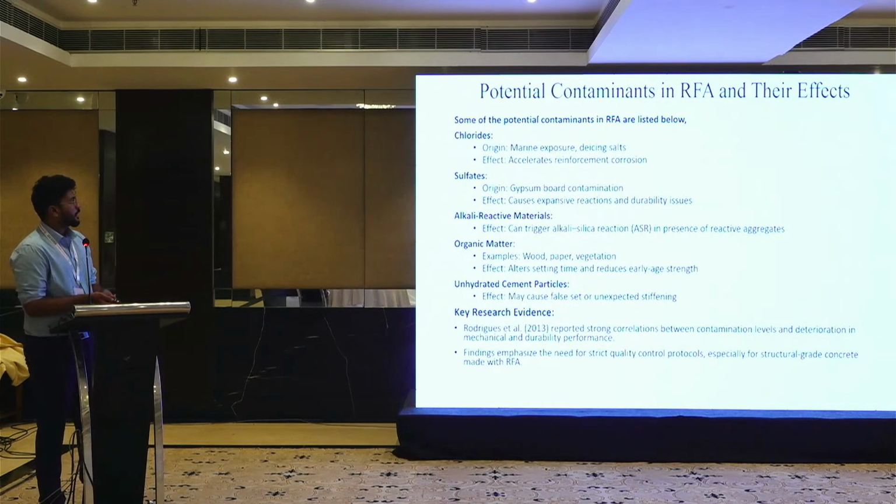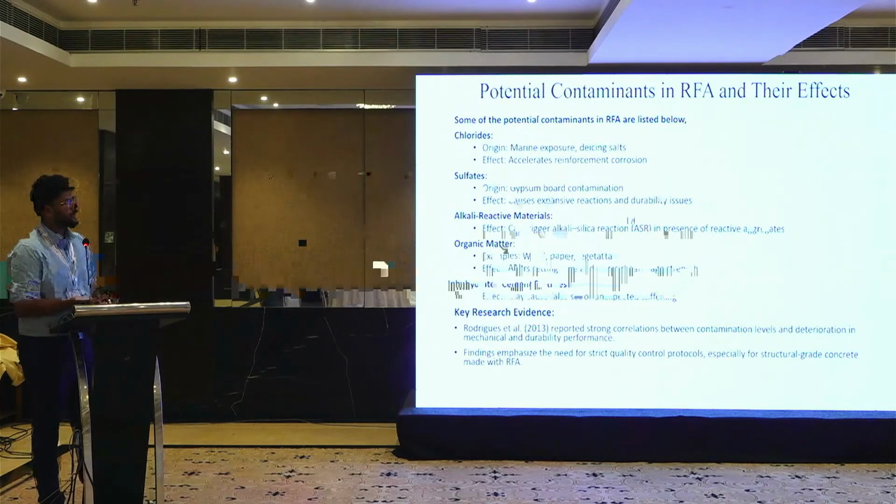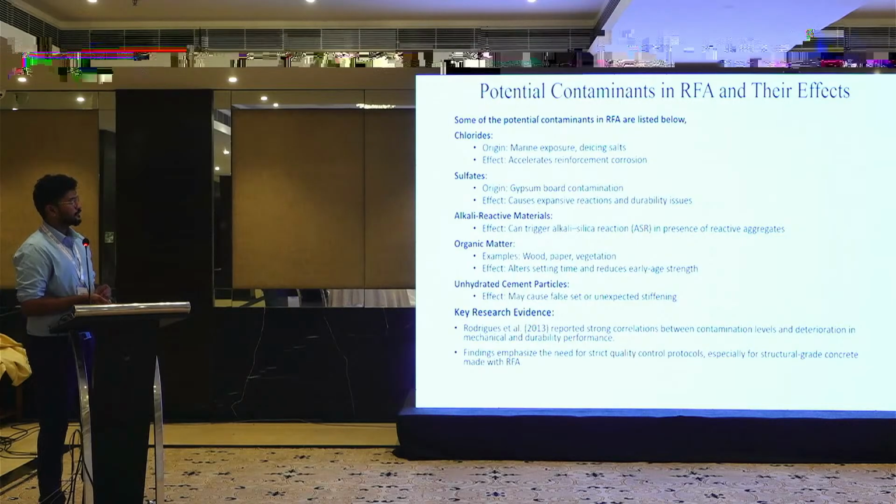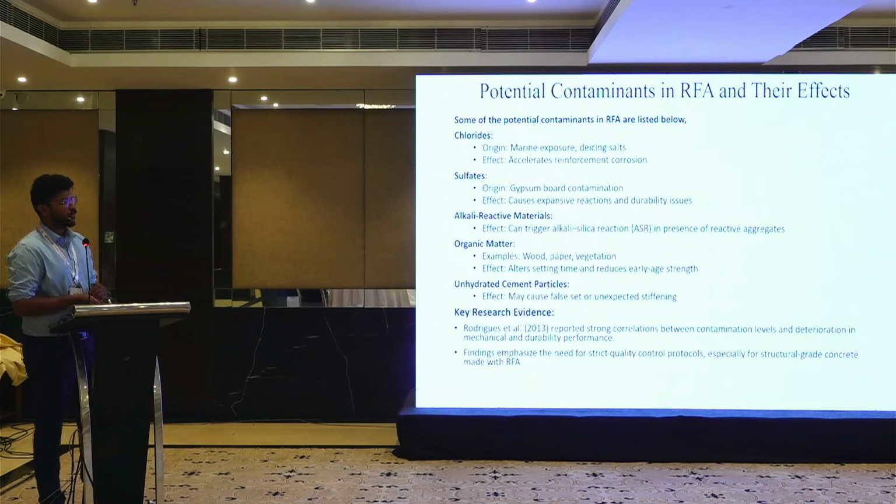Chlorides: marine exposure, excess chlorides. Sulfates cause extensive damage. The presence of reactives alters setting times and reduces early-stage strength, and unhydrated cement particles may cause false set or unexpected stiffening.